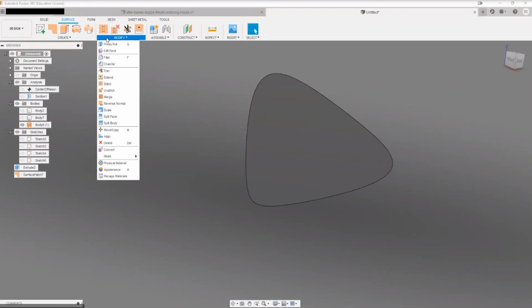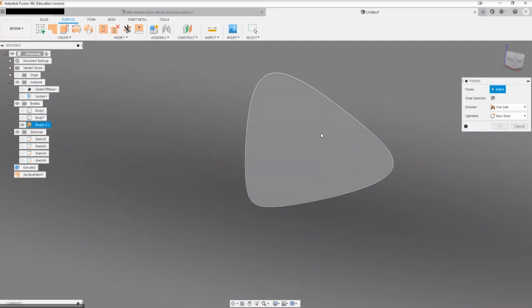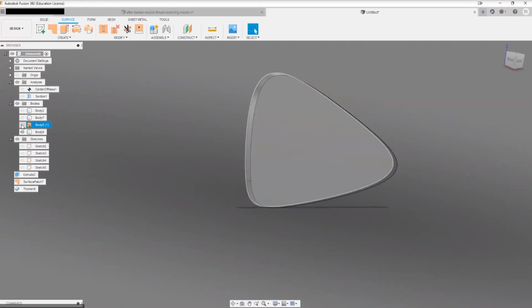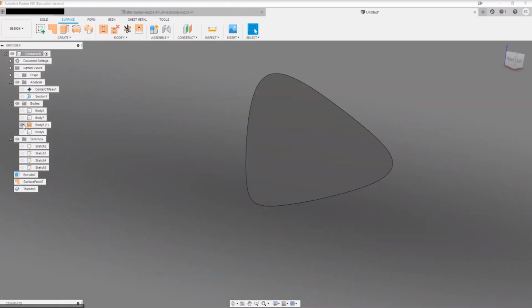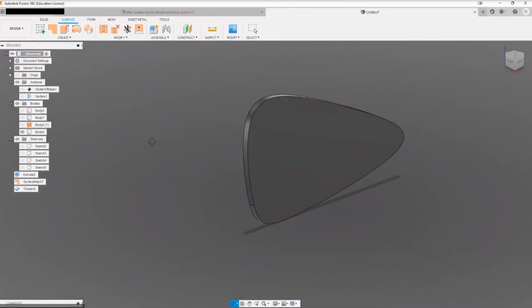But what we see over here, you can create thickness out of this, right? So you take that component, hit thicken, and suddenly this is a 3D part. Previously you had just an infinitely thin 2D surface, and now you've got a component like this.